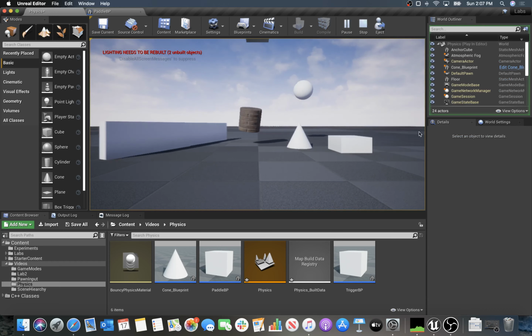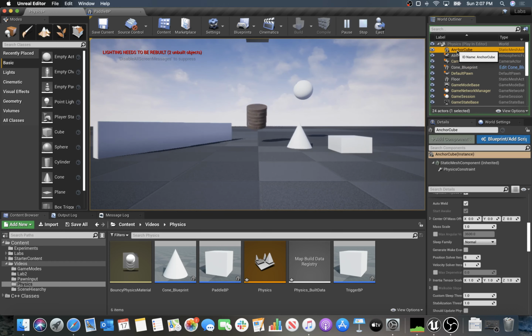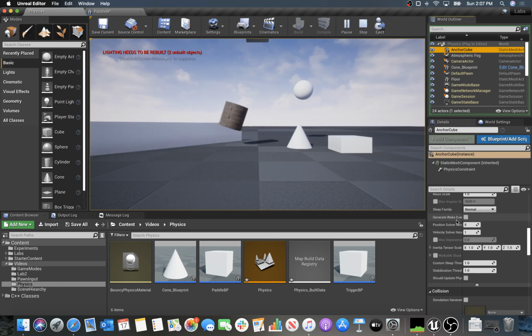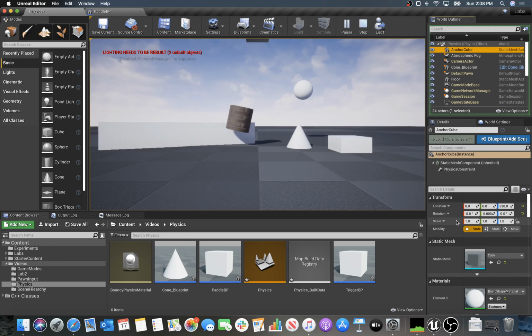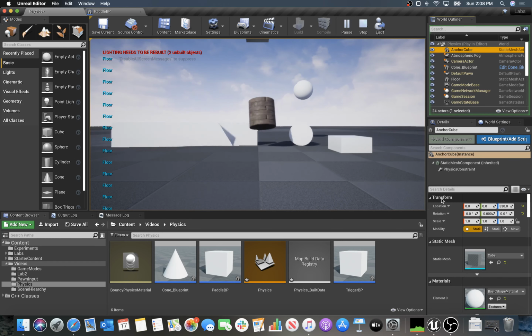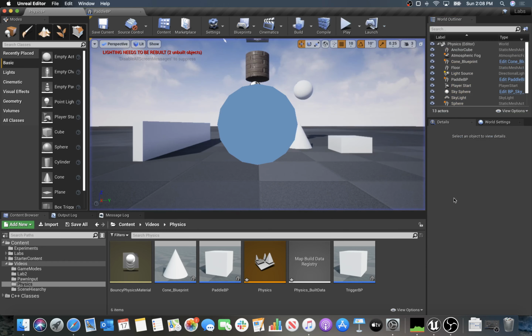And it just gives it some different behavior. It's really a question of what do you want it to behave like? Do you want these soft constraints to allow it to bounce around, or do you want more solid constraints? Solid would be more like a rope, whereas this is more like a spring instead. And then you can set the same things up for the angular motion, right?